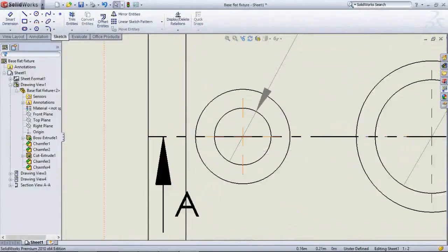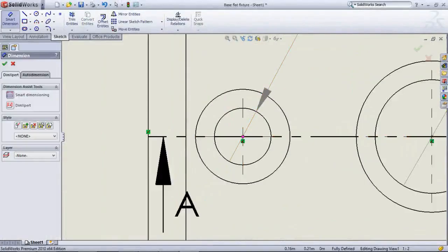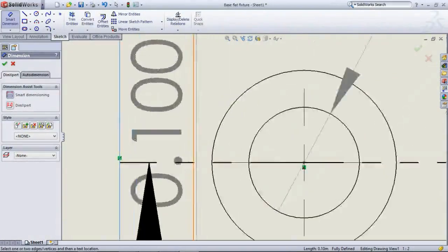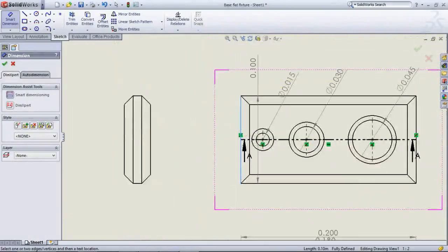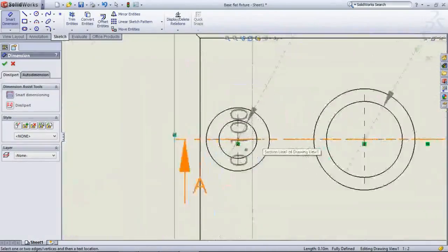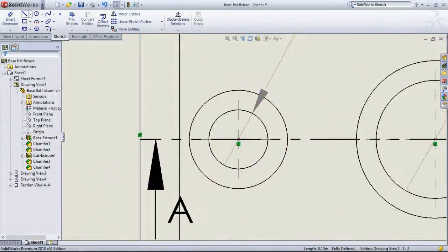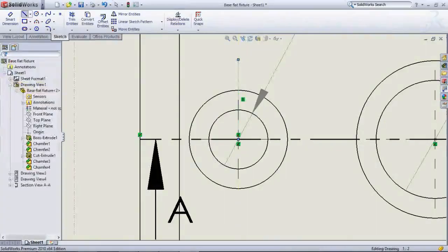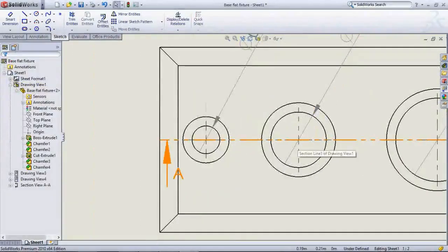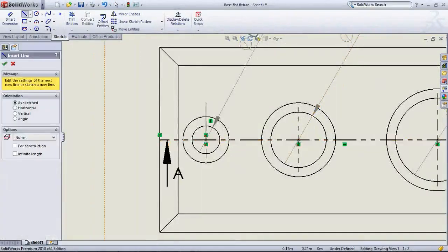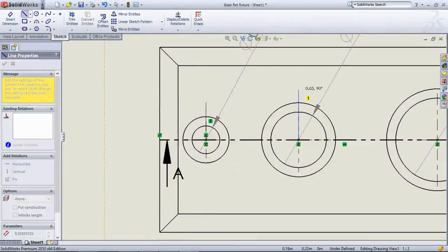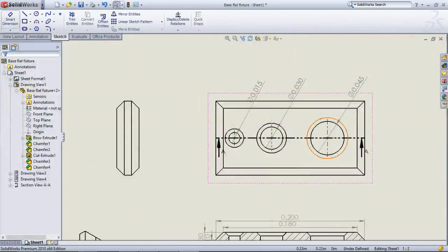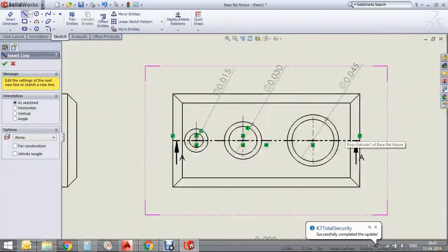Here three holes are mentioned. From here, the left side edge is used as a reference line. From the left side of the edge he will fix the first hole, from the midpoint, 25 mm away, then 50 mm for the other hole, and another at 75. So he can understand the coordinate of each hole, and what the center point or origin of each and every hole is.